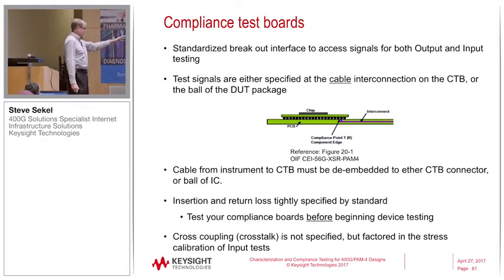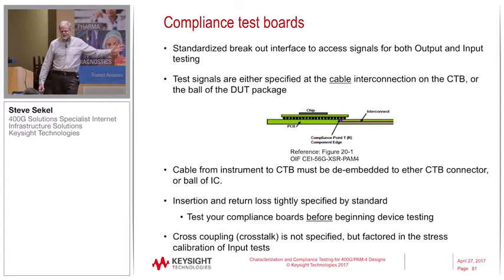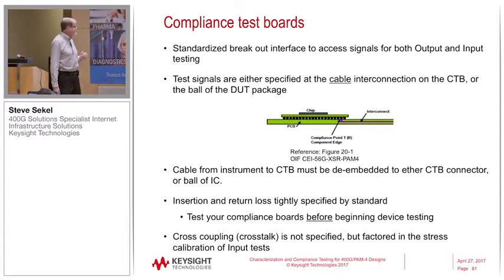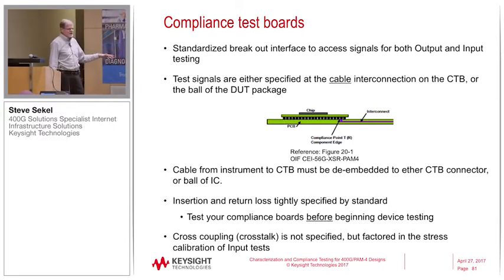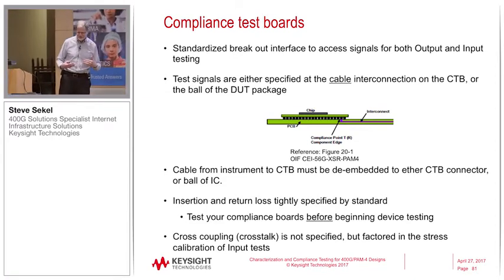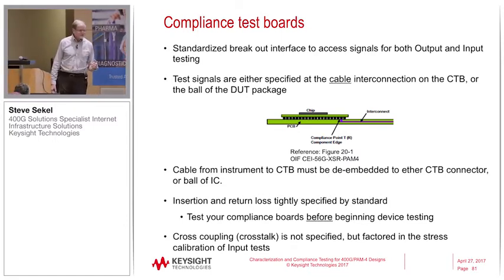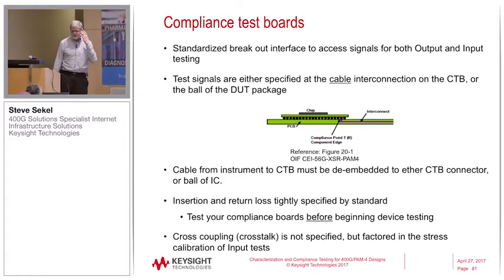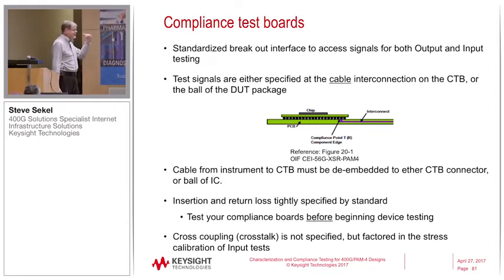Be sure you test your board before beginning. It kind of goes without saying, but you'd be surprised. I've worked with some IC designers that got far along in their characterization work and then started seeing non-repeatable results and said, boy, I wonder if our compliance boards are in good shape. That's when they validated the compliance boards and found out that they were not actually designed to the standards. So before you start taking a lot of data, it's a good thing to validate the board itself, and that includes the purchased ones.